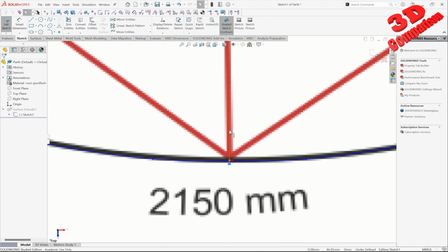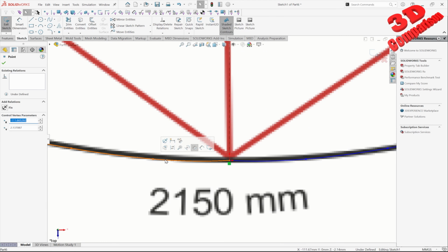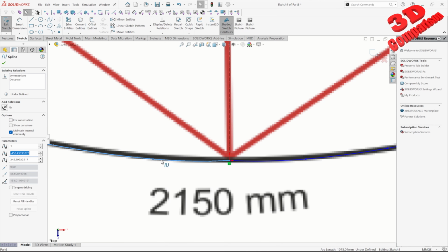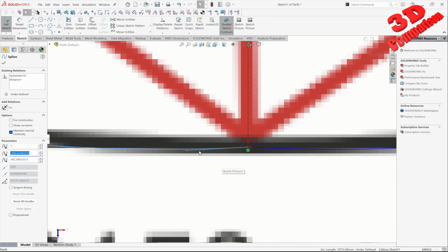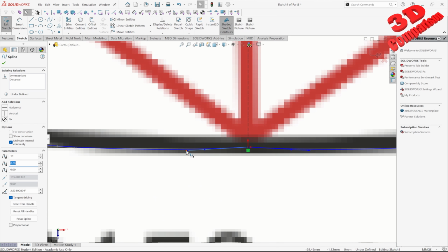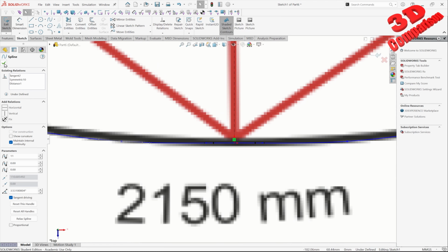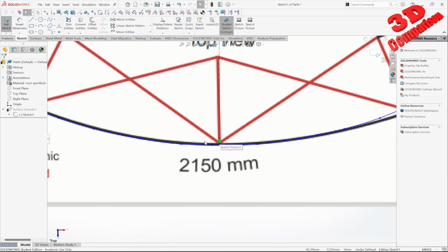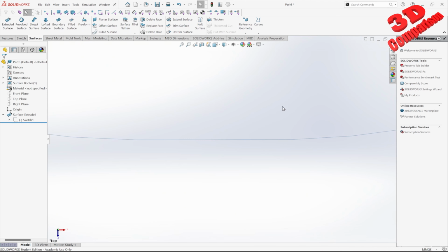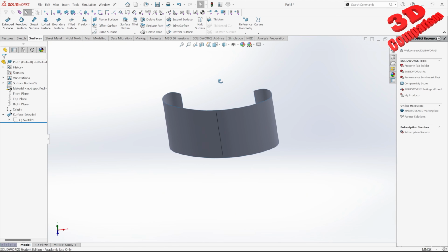If you don't want that middle edge to be visible, we have the possibility to select this spline. So we see this arrow. I can select that arrow and I can make this horizontal, and we see how that changed. And now we're going to have that tangency added. That means the intersection point will not be visible.